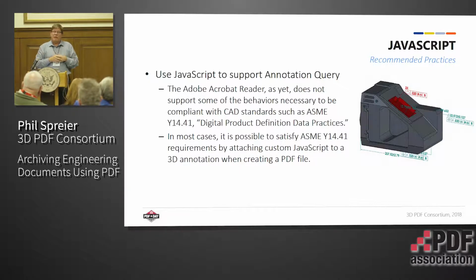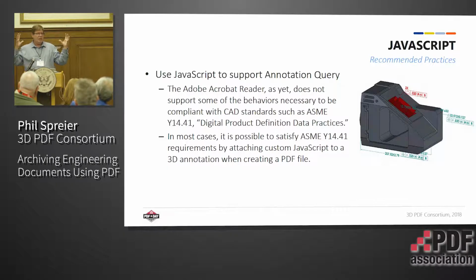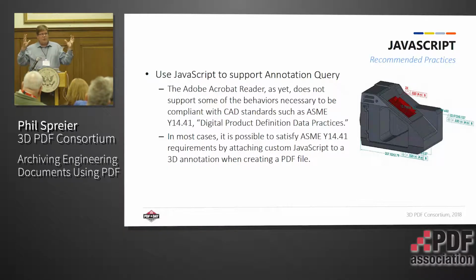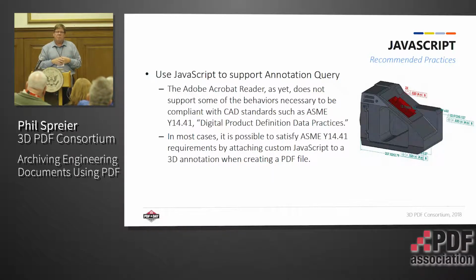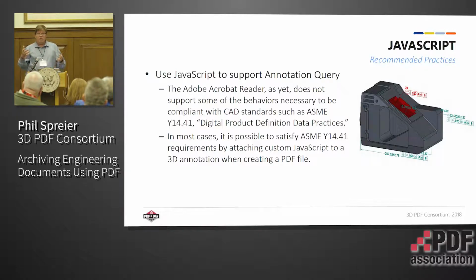Well, that's great, but this is a carbon fiber tail section, right? And so when you begin to drill in it, it's a little bit more difficult to fix one of those than it is a standard metal piece. So they went out and they drilled a whole bunch of holes into this thing, and they were all wrong, right? And the reason that they determined that they were wrong was because there was no visual feedback.